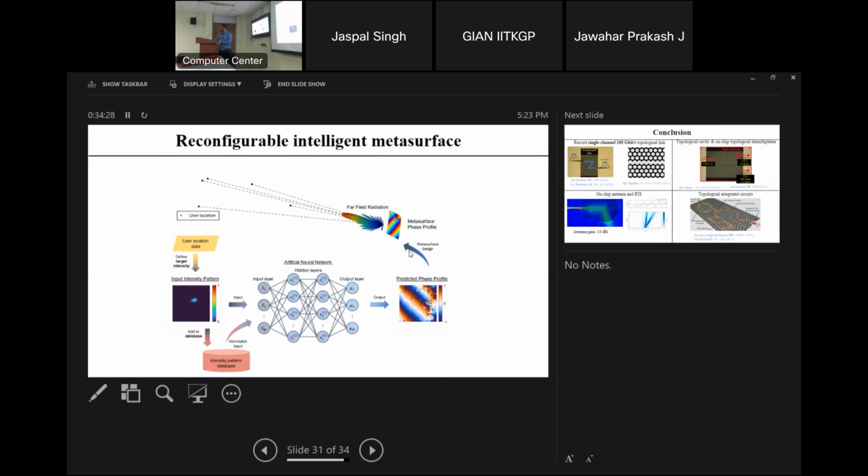Yes, the MEMS actuator, MEMS and NEMS actuator. That is the one thing that we wanted to do. But one issue with MEMS actuators is that first, they are slow. The speeds are in the millisecond range. But that is the only way we think it could be done, so we are working on that one. And the second problem with MEMS is that they are metallic in nature.